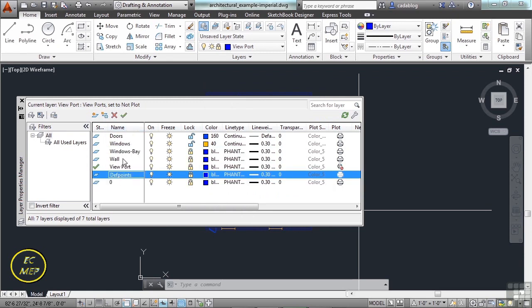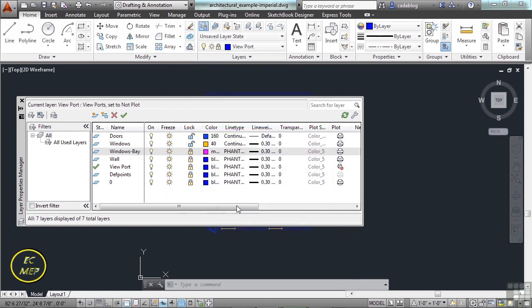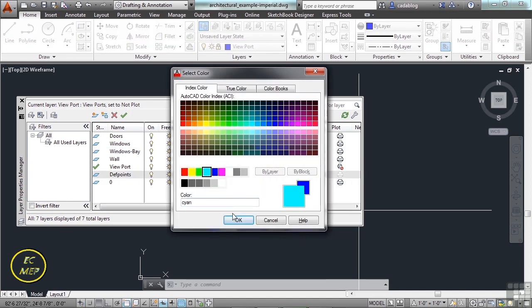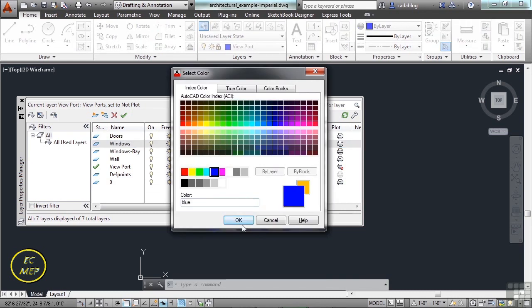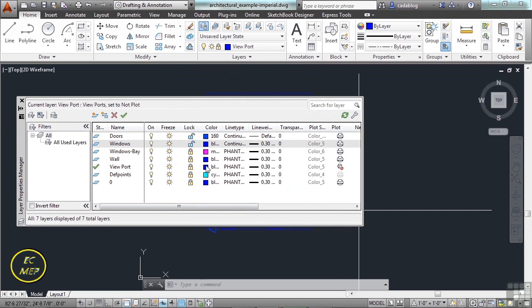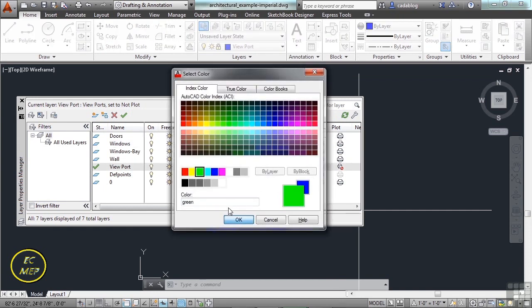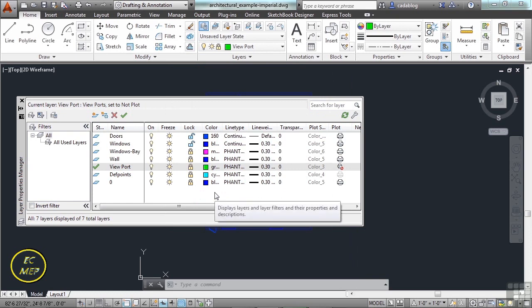And remember, when you're picking the layers, pick them over here in the name or in the status. Otherwise, if I pick over here, it's going to open up my color change, and that's what it's going to want. If you only need to edit the color of one layer, then that's fine. Click it, change the color, and there you go. That's a quick way, and it eliminates one step of picking again and picking. So it's going to take off one or two clicks. But that's all you have to do to create a new layer or to edit a layer.